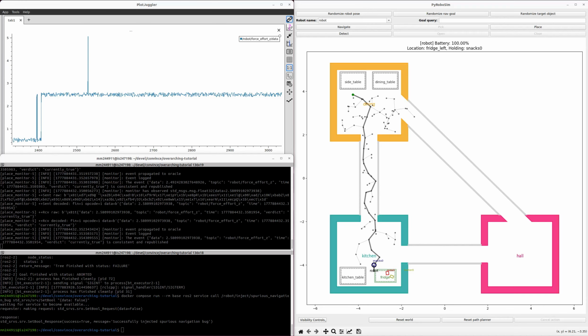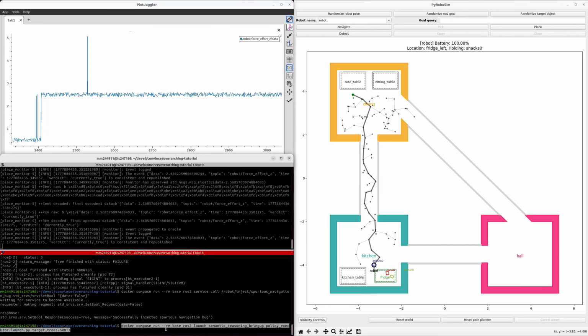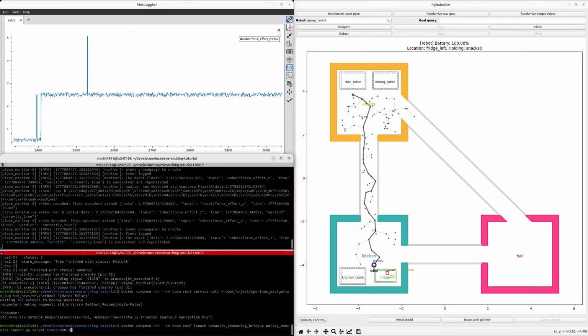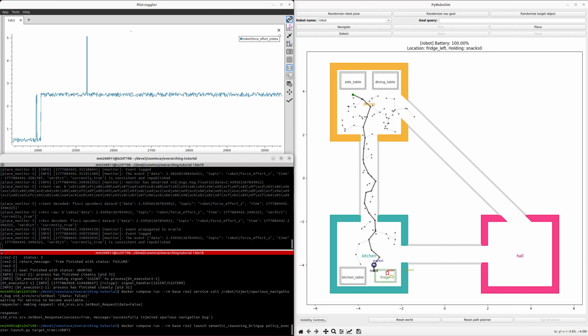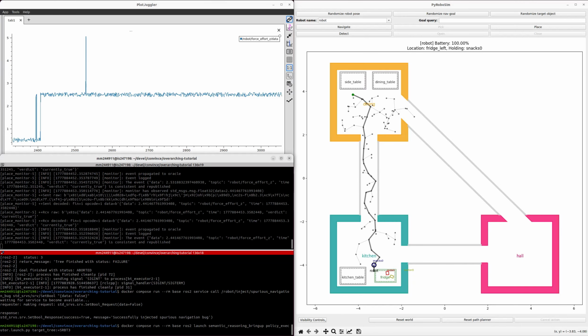And now we can finish our mission with the action that is determined by the planner, knowing what was the cause of the failure. So the mitigation strategy is going around the kitchen to recalibrate and avoid the drift behavior, and then go to the fridge again, this time ending in front of the fridge.